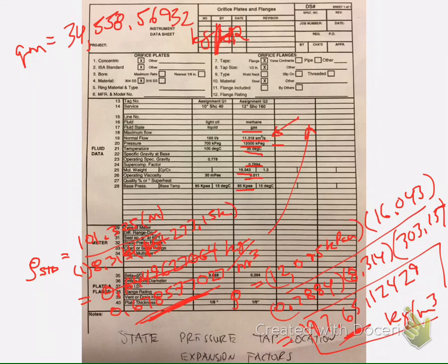And the viscosity here, it's kind of hard to see, but it's right there, 0.011, and it doesn't give us the units. Let's just have a quick check here. I'm going to assume that it's in millipascal seconds. Yep, it's in millipascal seconds. It's not showing there, but it should be. So that means you need to take 0.011 and divide it by 1,000.